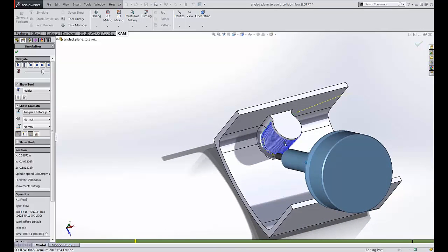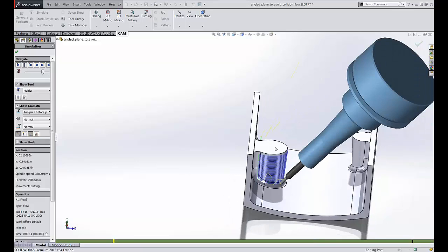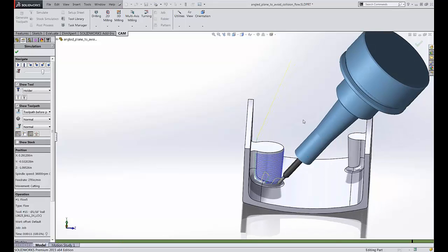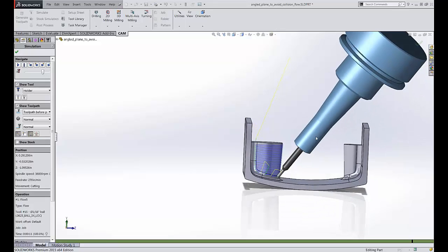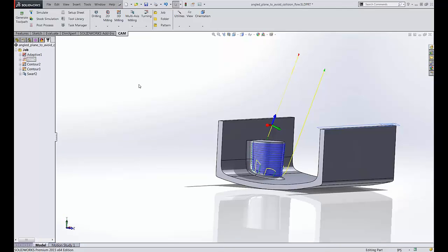Your initial tool vector has a whole lot to do with how that cone allows movement to progress. Right, that cone that the minimum or the maximum tilt is allowing is entirely based off of that Z vector, off of your tool orientation vector. So keep in mind you can use that to tilt everything in directions that otherwise you just don't have the handles for.